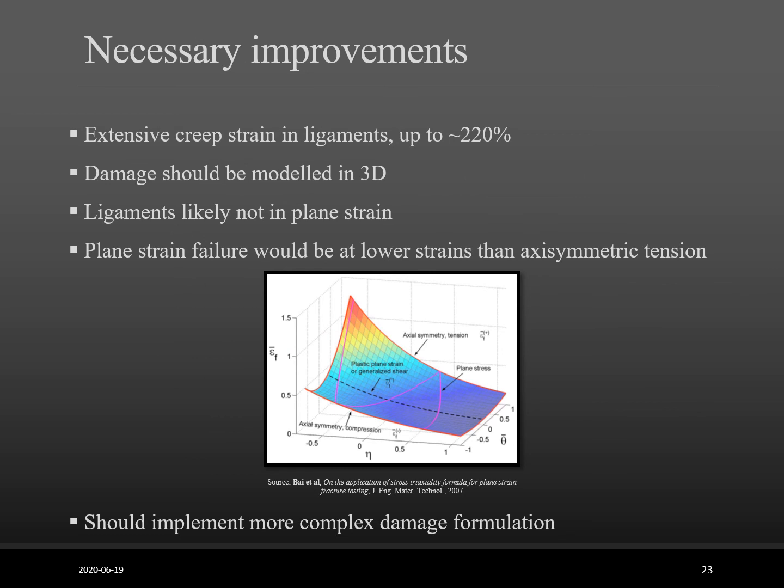However, as mentioned previously, the level of creep strain exhibited is not physically possible, and the ligaments that experienced these high strains would have ruptured, but creep damage was not implemented in this simulation. Therefore, various improvements to this model are necessary.